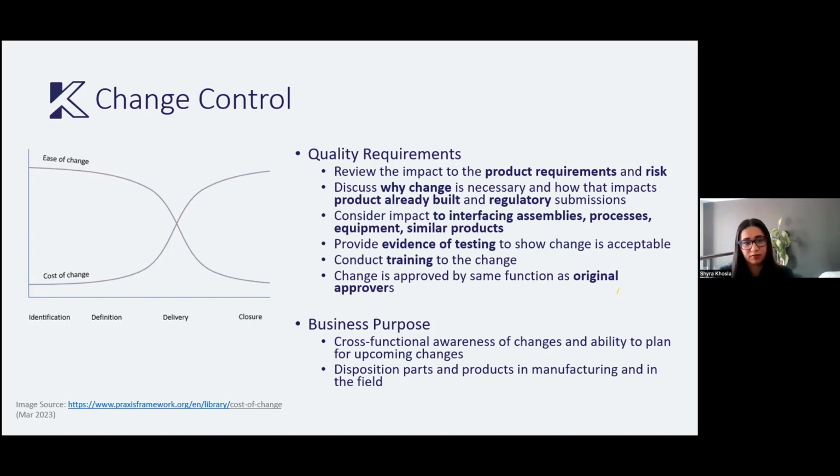So it might seem very simple that you are narrowing tolerances on a part, and so that maybe should just be a quick engineering sign-off, but that's not generally the case. And so you're looking for cross-functional review, and typically with an engineering change like that, it's engineering, manufacturing, quality all need to be involved, but many times it also involves regulatory, purchasing, supply chain, material handling. It can expand depending on the scope and the roles within the company.